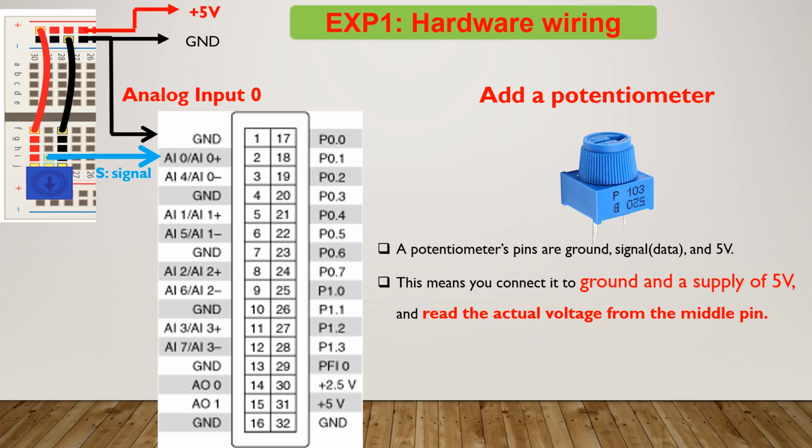In the first example, we want to connect a potentiometer to an input of the data acquisition, such as AI0 or analog input 0. As we talked before, how we can wire a single-ended analog input to data acquisition. In this example is the same.